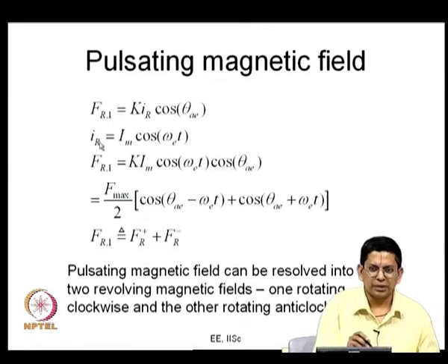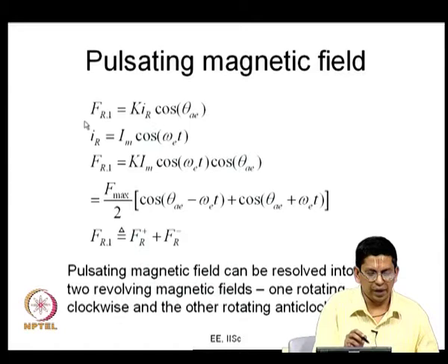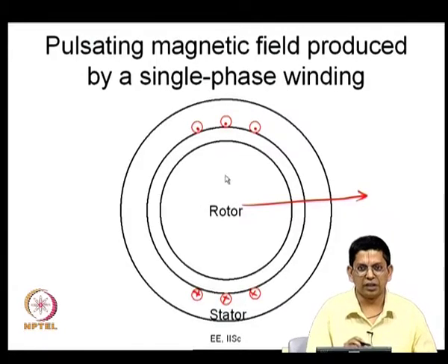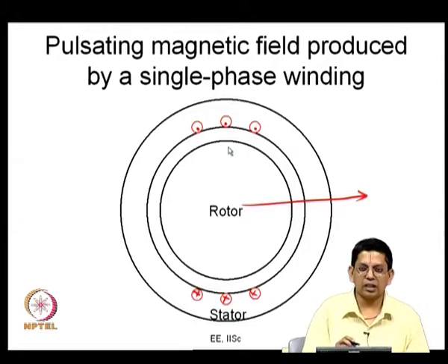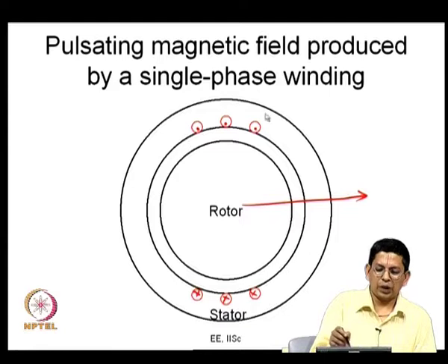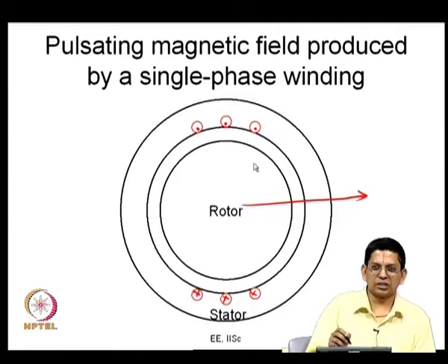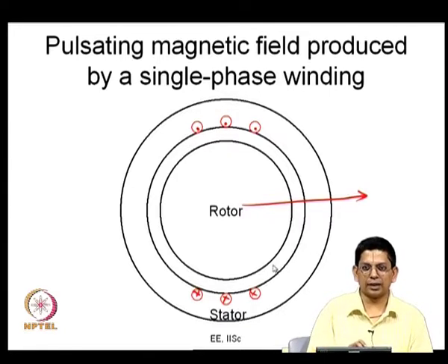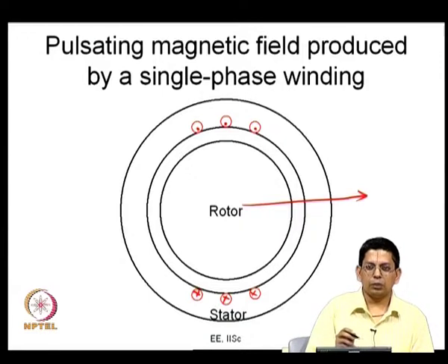And 1, basically whatever MMF is produced by a winding, like what you have here, would be some alternating waveform. It need not be sinusoidal, it will not be sinusoidal. To make it closer to a sinusoid, you do a few things: you design this, you distribute the windings and all that. But still it is not sinusoidal, and in most machine analysis you ignore the spatial harmonic components and deal with the fundamental component.